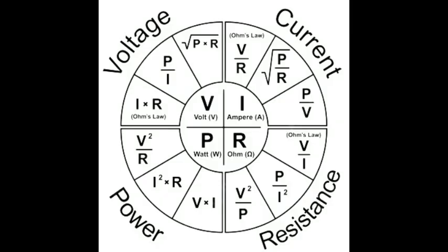Now I can go ahead and solve for resistor number 1. So it's going to be 40 divided by 5. That's going to be 8 amps. 40 divided by 20. That's going to be 2 amps. This is going to be 10 amps. And I can go ahead and add them up, right? 10 plus 8 plus 2 gives me 20 amps. So, okay, we're doing it right.